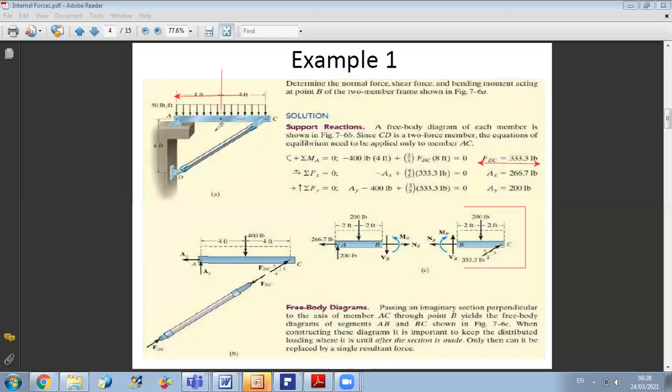No. And here, if you consider that I have only a force at B, then when you do a cut, for example, here, you will not have any load acting on the B, which is not the case. So if you want to calculate internal forces, you do the cut, then you reduce the distributed load. So here, when I do the cut at B, what is acting on my remaining part is a distributed load. And this distributed load, I can now reduce into one equivalent force.